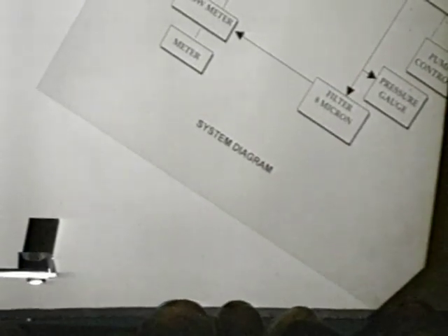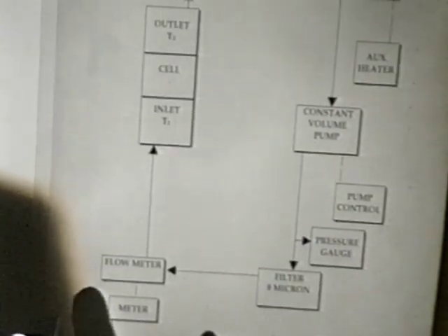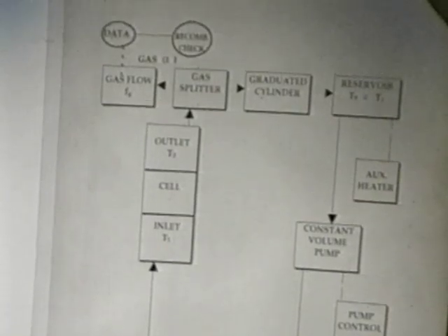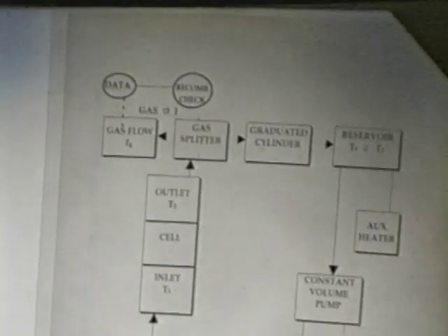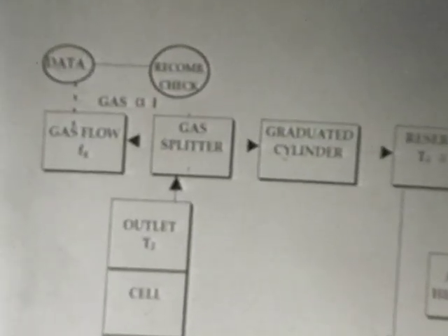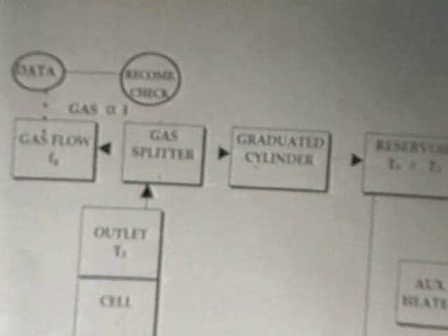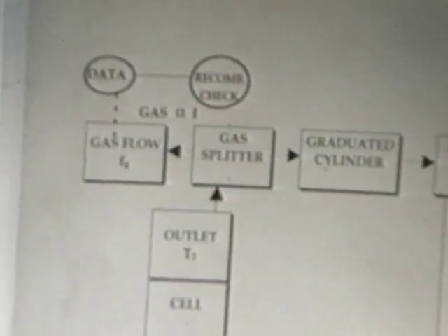Analog meters, I don't necessarily believe all the time. Our gas recombination, we do measure the gas flow. It is not very accurate at low current settings because the air comes out as bubbles. So it comes out in bursts as opposed to continuous flow, and the meter doesn't like that. At high current readings, it does let us know that we don't have recombination.